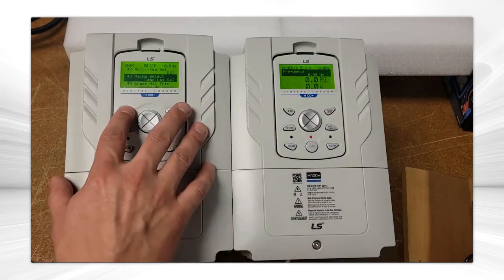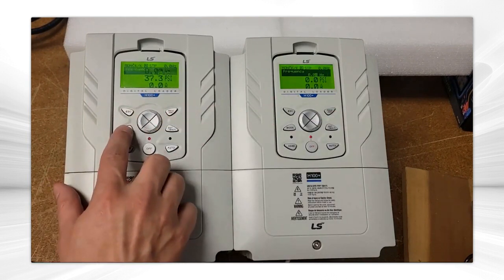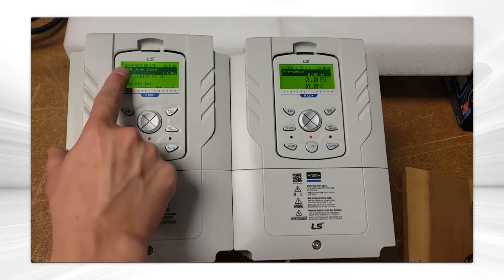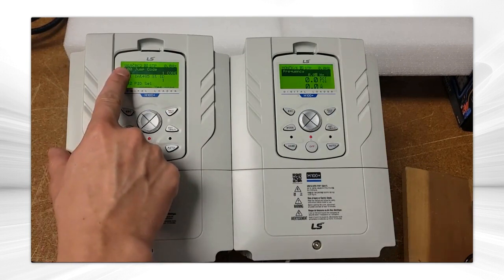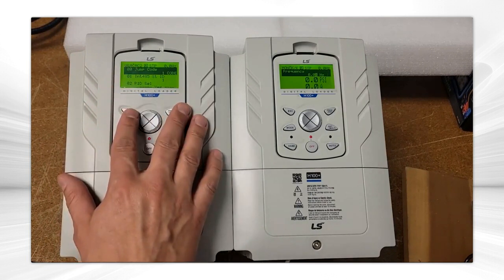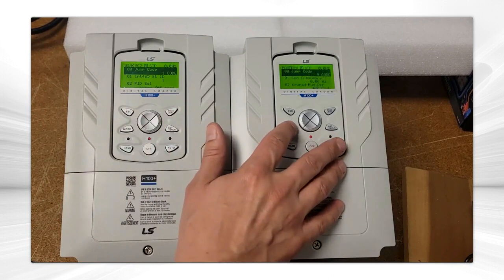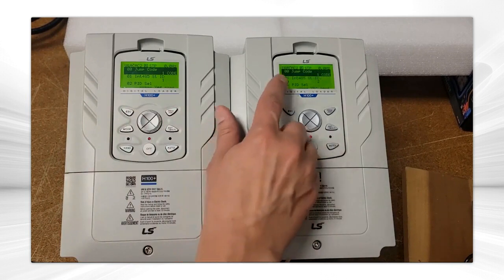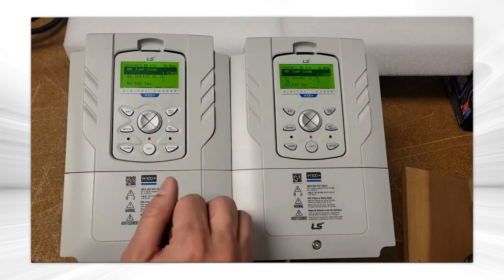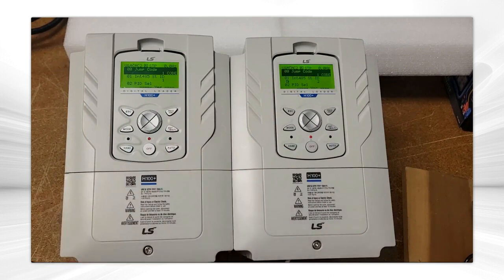So this drive is the same. Another way you can tell that it's set up is if you press your mode key. This is your parameter mode. Press mode again, and this is user macro mode, UNM macro 2. So this is the lead lag macro. I'm going to go to that on this drive. You can see it says the same thing, UNM MC2, so it's the same macro. I really didn't do much programming on these. I enabled the macro, which sets up most of the programming for you.